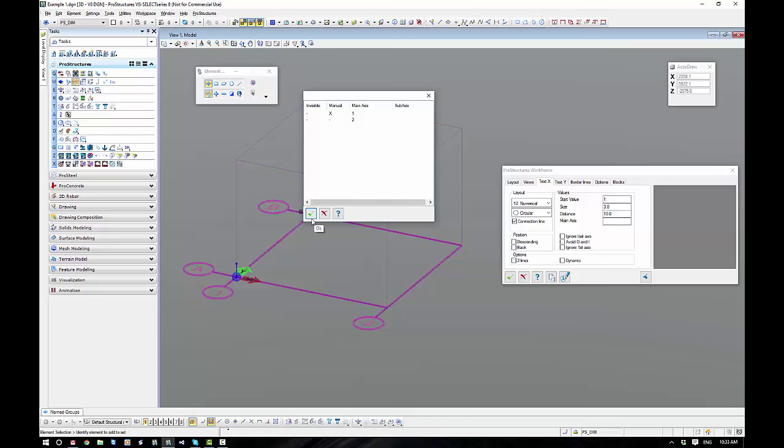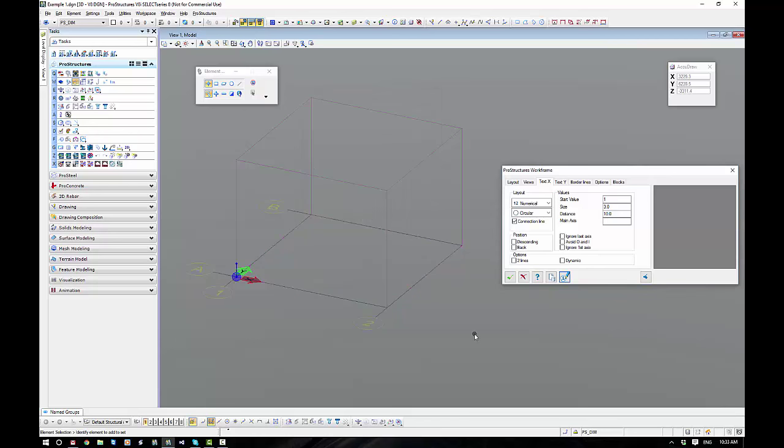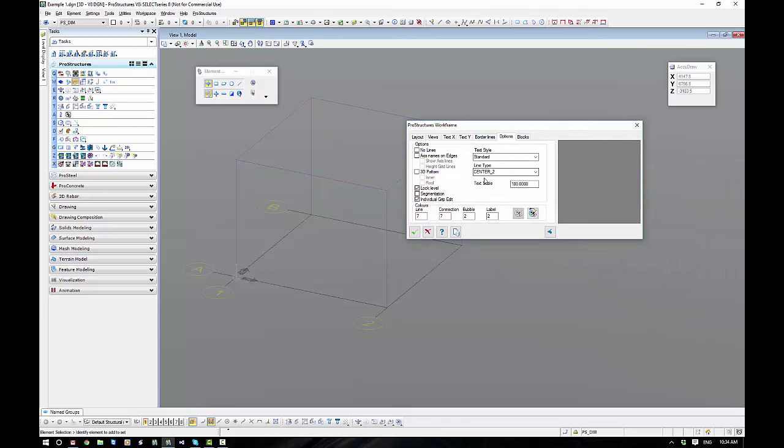Okay, hopefully we've got all that. Final thing is our options. Key thing within our options to remember, -1 would be the default configuration. You can see here I've defined colors. Our text scale, things to remember is don't forget your text scale. The line type is center 2, and that is for the main grid. And your text style is standard. Really important here, don't change that from standard.